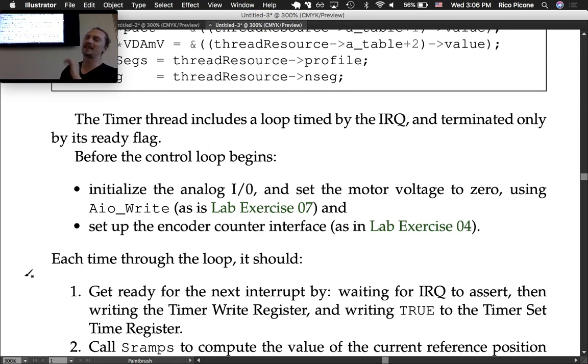It's a nice safeguard in case there's an issue while you're debugging. After the first time through the while loop, it should be whatever you're setting it to, so it should be fine. But especially for debugging, it's nice to have that to make sure it sets it to 0 instead of some other wild value. And it saves you from hitting the emergency stop on the amplifier.